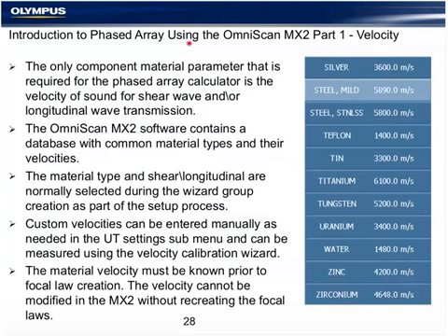So that was 2 of our 3 hardware parts: probe, wedge, material. So when we talk about material, the 3rd part, we're really talking about only velocity. The thickness of the material, the width, the weld bevel, all of those things can be modified after beam formation or after acquisition and reverse engineered in the data if necessary.